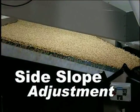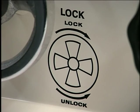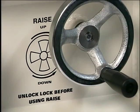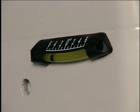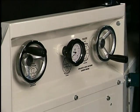To adjust the side slope of the deck, first rotate the clamp lock hand wheel in the labeled direction for 5 to 10 turns. This will release the clamping mechanism that holds the deck in position. Now, rotate the jack hand wheel in the labeled direction to either increase or decrease the side slope. The angle of the side slope can be verified by looking at the bubble level located on the back side of the table. Finally, rotate the clamp lock hand wheel in the opposite direction to secure the deck.